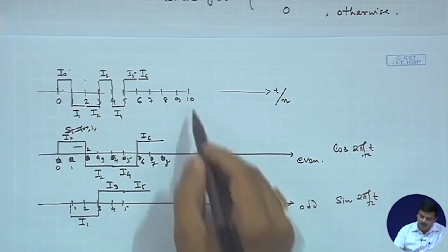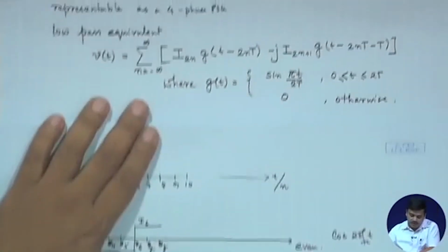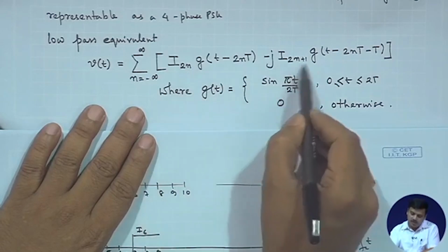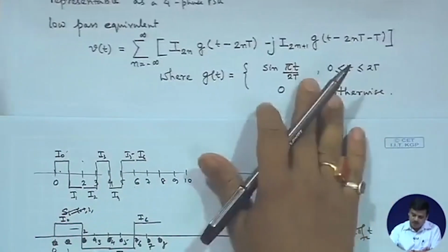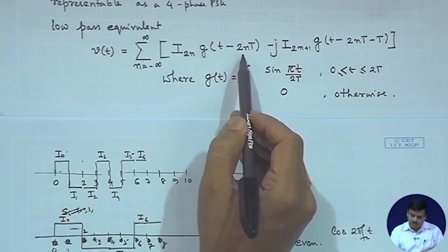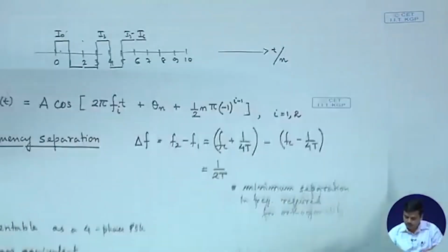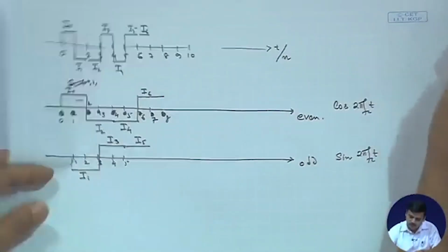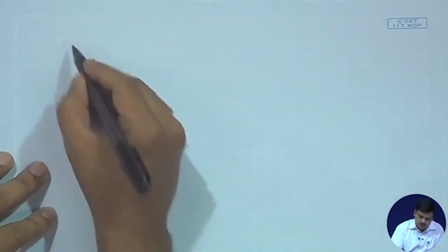So, overall my bit rate has not been hampered between these two, and when I write it in this form, this modulates the cosine carrier, this modulates the sine carrier. So, that is what we have. So, if we would now look at what is g(t minus 2T), things would become a bit clearer now. So, if we would look at the expression of g(t),